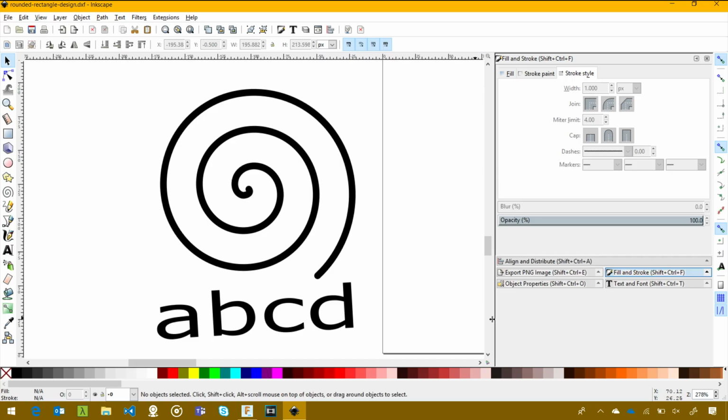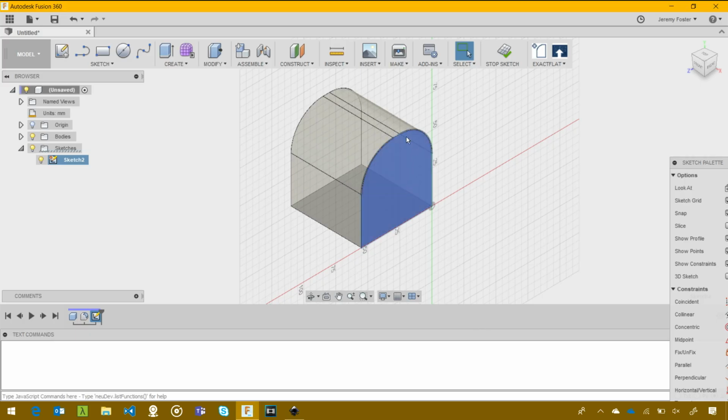We've saved our design out of Inkscape, and we're ready to jump back over to Fusion 360 and bring that into this face. Now, in order to get our DXF file, I actually right-clicked on my sketch, and I said Save as DXF. I had to create a sketch first, so I already have a sketch. And in this sketch, this is where you import a DXF. You can actually import an SVG as well, and you might notice that in the menus here, but I've discovered that you get better fidelity of the units if you do it as a DXF than as an SVG. If you bring it in as an SVG, it's going to maybe not show up at the right size or in the right location.